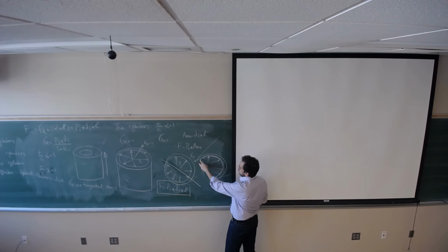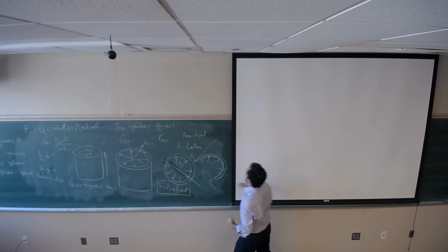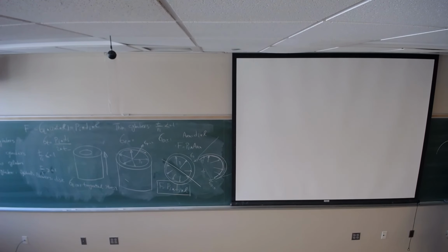basically, if I have this, which is the half parts of the cylinder, and the internal pressure is applied here. If we measure the force, we will see that the effective area is going to be this line times this length.